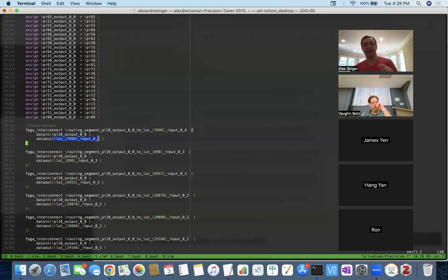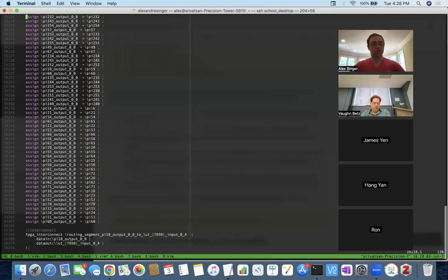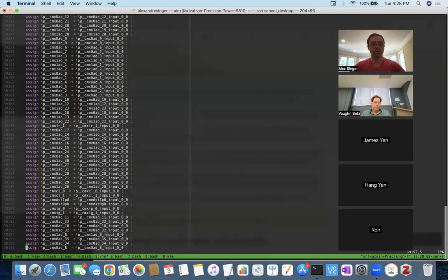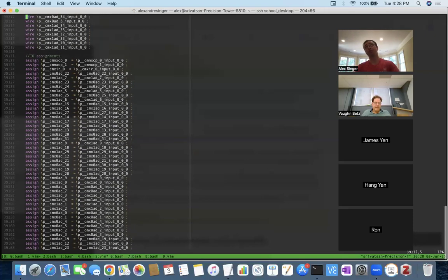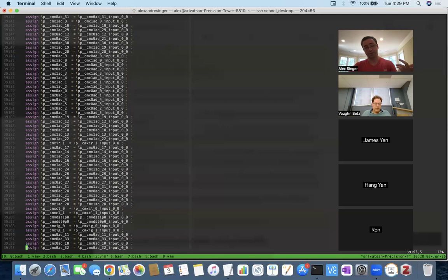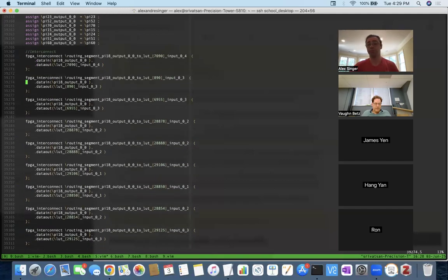Well, we want to actually annotate the delays of these wires. If you just use regular old Verilog wires, I don't believe it's possible to annotate the delays onto the wires themselves using an SDF file, which I will explain in a moment, and which we use for OpenSTA. So it's important that we're able to create these fake modules that can pretend like they are a wire which has delay annotations on it.